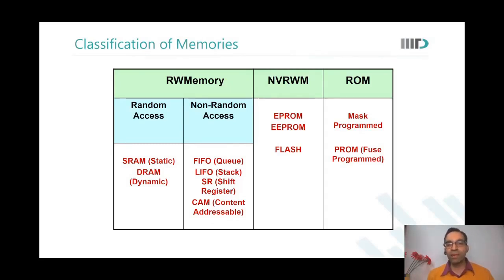Now which port do I send my next data packet to? So I search for America and identify which port America is programmed at, and so on. So that is content addressable memories. Again, non-random access. I do not give any address to the memory. I just give a content, and the remaining information at that matched address is given out to the user.